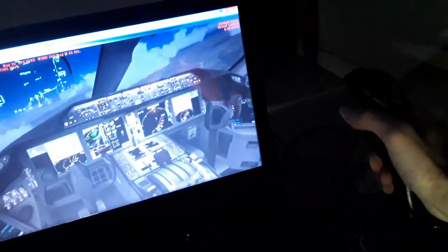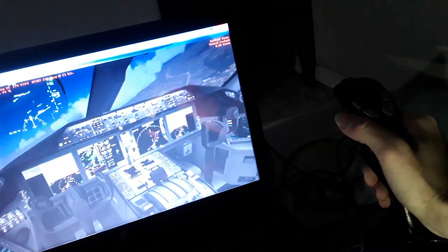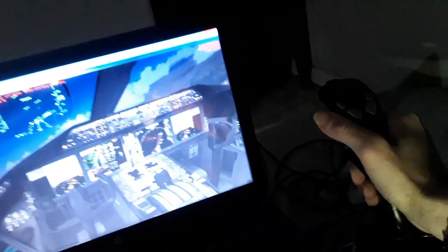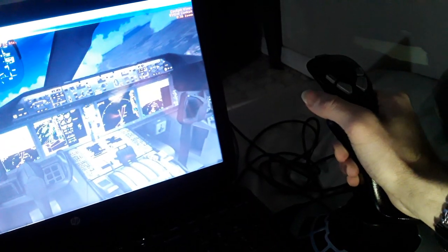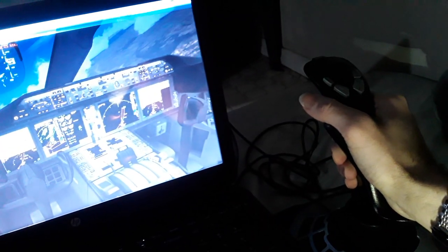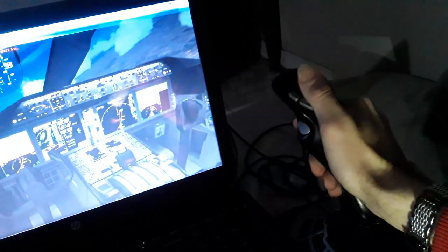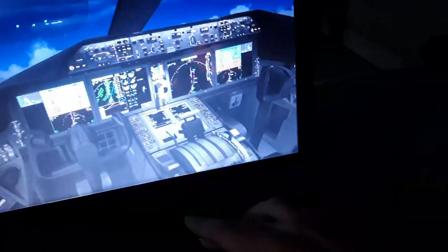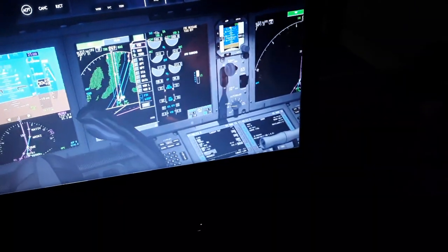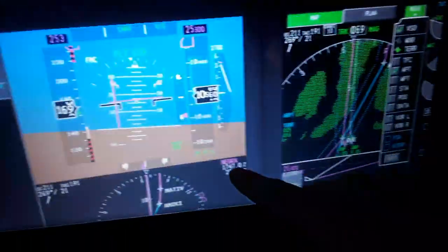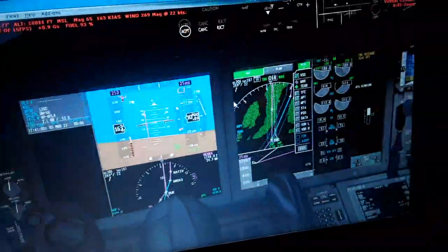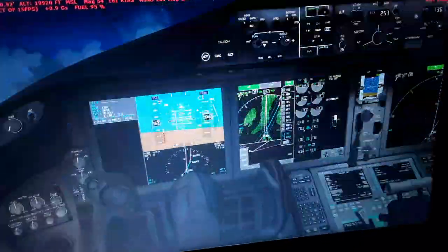So we're going to lose some weight from the fuel on board. We don't need to have as much fuel. So we make a turn now. Keep climbing, 10,000 feet, the airspeed 170 knots, to align 35 nautical miles. The next waypoint over here. We pass the Zui waypoint, as you can see.